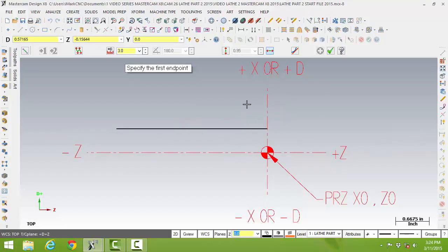I'm going to create a horizontal line again, touching the origin, snapping to the origin, and now I can touch the end of this and I'm set. I can apply that. Looking at it, there's a diameter of a 1/2 inch, so I'm going to go from the origin to 3 inches, and if it's 1/2 inch, I'm going to put the whole value in my dimension, but it's only going to go half the distance.